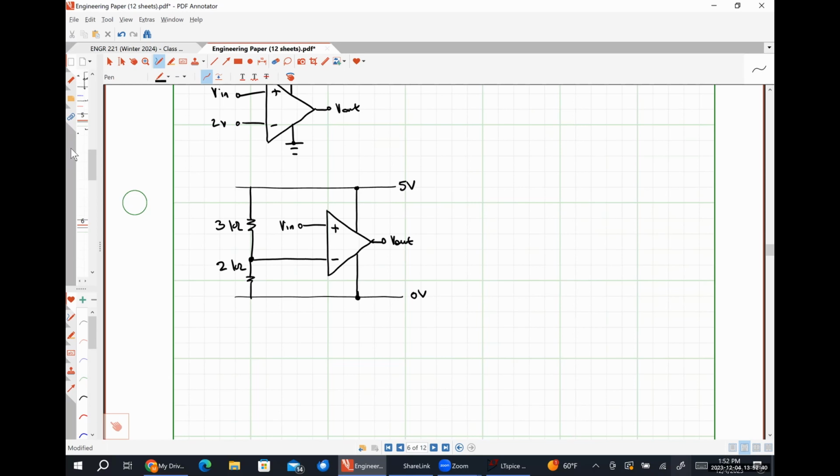KVL around the loop, negative 2 Vx. But because the positive terminal of Vx is over here, that VX would be the negative. The positive polarity terminal of Vx is on the negative polarity terminal of the 30-volt source. The negative polarity terminal of Vx is effectively the positive polarity terminal of the source because there's no current flowing through that resistor. There's no voltage. And then you'll still get negative things.